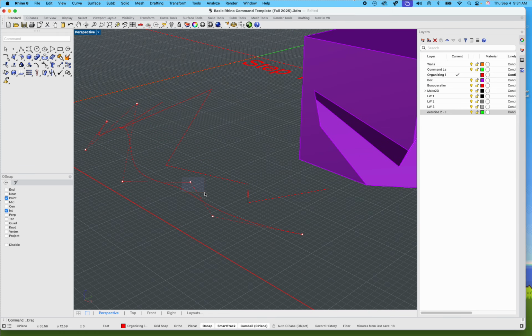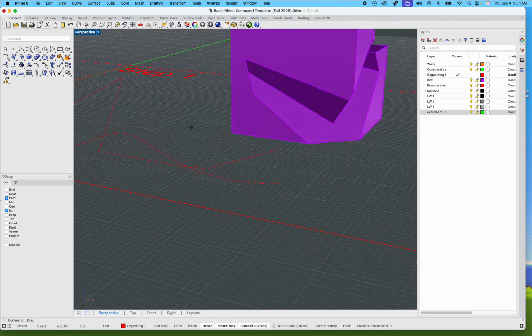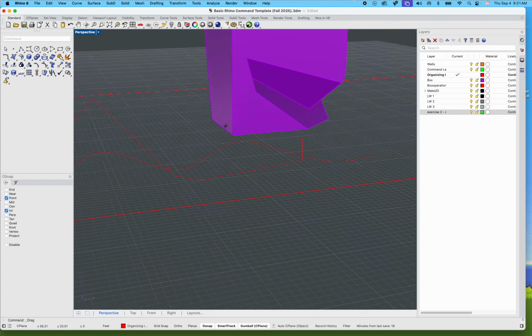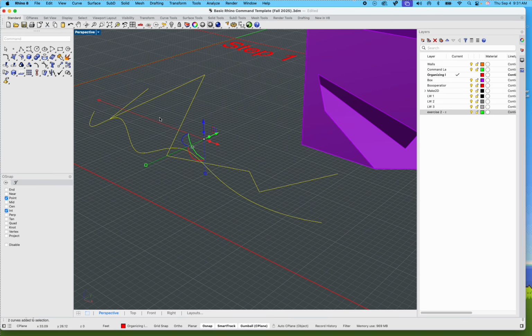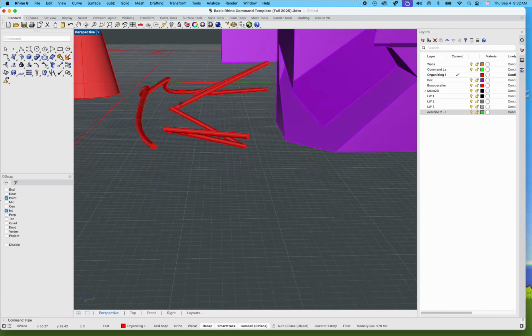How many of you guys struggle with making a roof in Design Studio? You can make roofs now. Anyway, we'll get to that a little bit more. But at least in terms of pipes and rails and all those wonderful things, we can just type in pipe, right? So if you type in pipe, it's actually going to ask for that radius. In our case, it is in feet. So when it says 1, it's actually saying 1 foot. So if I want actually another dimension, I could put 6 inches, enter, bam, 6-inch rails, right?